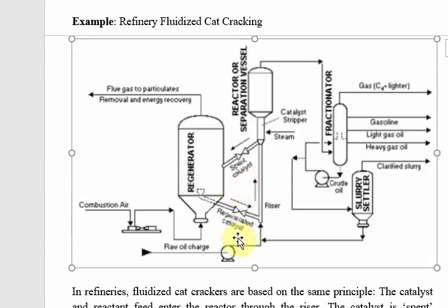The regeneration is happening in the riser line, something like that. So in fact, today, even though most refineries still have this kind of regen unit, actually no regeneration is going on there. It's actually in the pipelines that they manage to regenerate the catalyst.